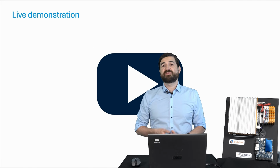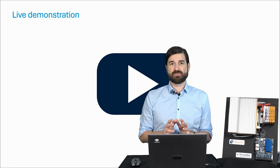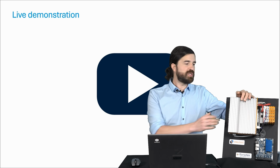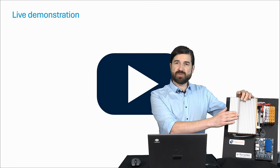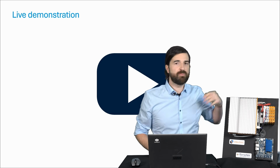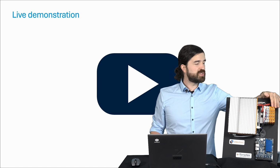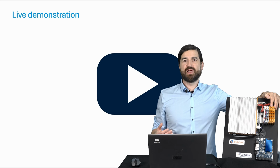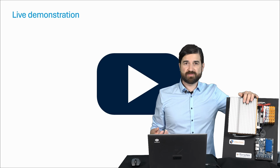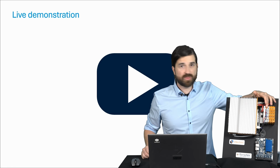But now I've talked enough, and I'd like to show you the whole thing live on a living subject. And for this, I've set up some hardware here. Essentially a multi-core IPC running Debian Linux with a real-time patch and Docker. Connected to it is an Ethernet coupler and a digital output board. The yellow boards aren't relevant to us right now. They'll be of interest for the upcoming presentation. On this, I'll now set up a virtual controller and use it to access these real I/Os.